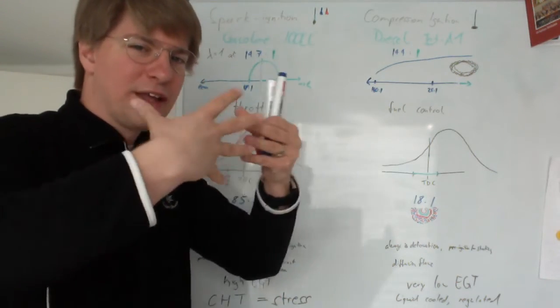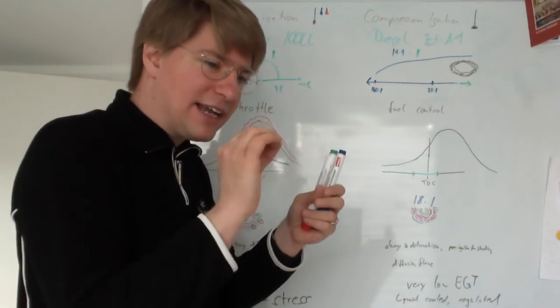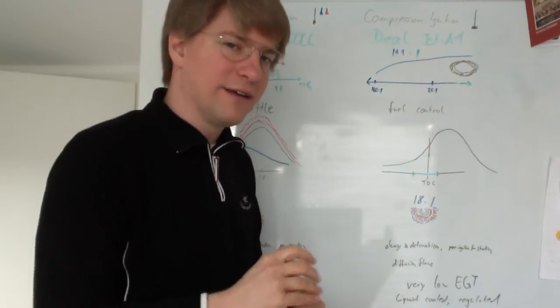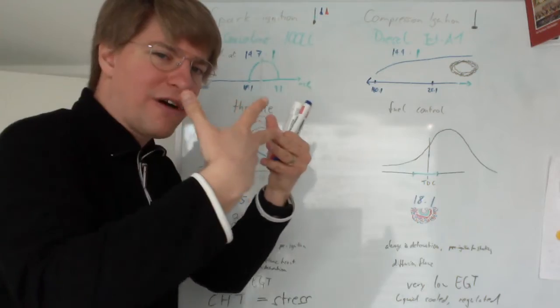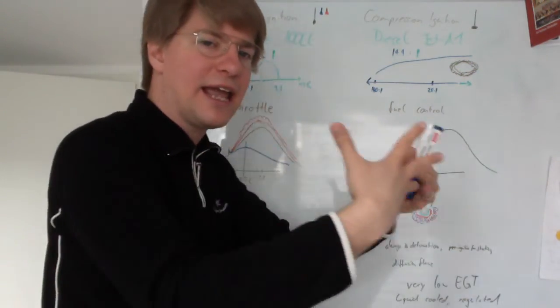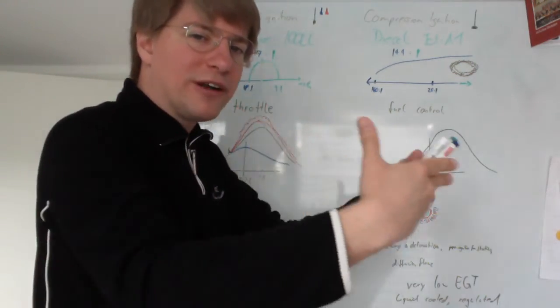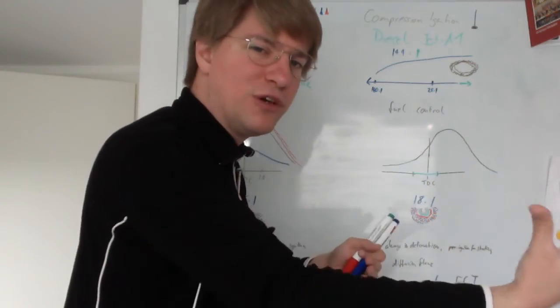So as the front of injected fuel, of those finely granulated fuel droplets, ideally atomized fuel, comes into the compressed hot air, the flame front moves exactly with this diffusion of the fuel into the air.